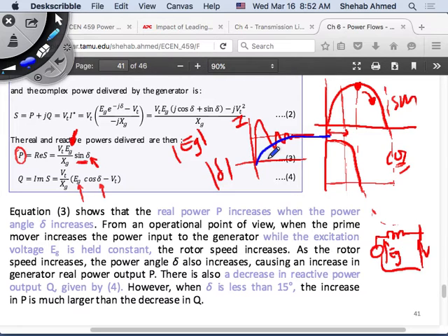These loads are coming on board, and you have to supply the load. Otherwise, generators will slow down and frequency will deviate. You don't want that to happen, so you have to be as fast as you can, and at the same time try not to have significant overshoots. That means when you have a load, this angle will change and bounce back and forth until it stabilizes at its steady state angle.